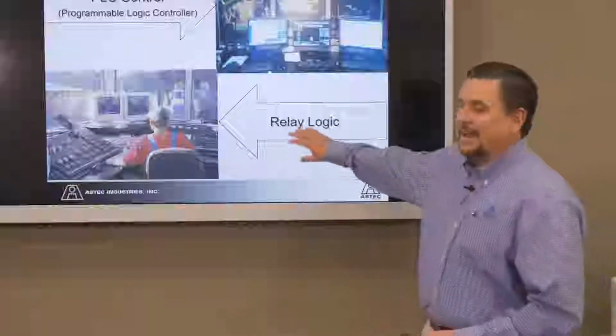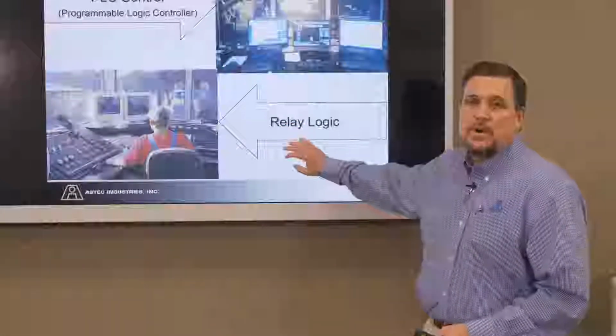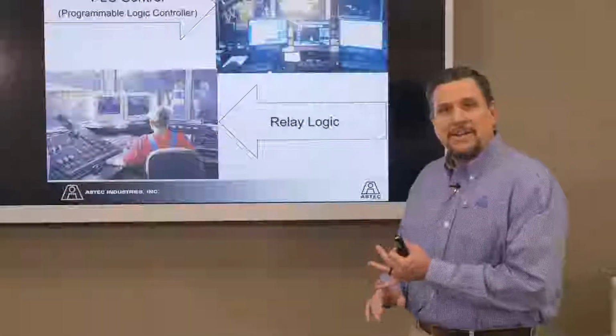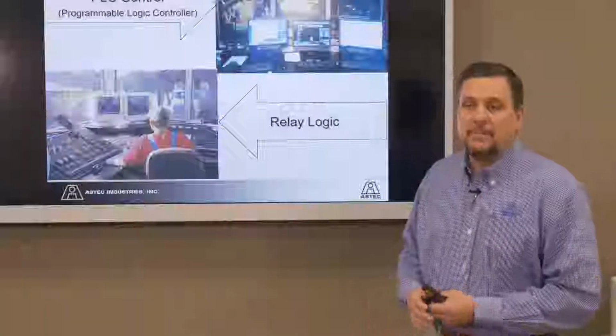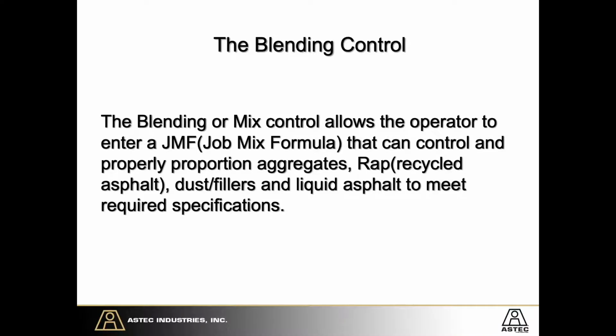Even on the older relay logic systems, when you looked at a blending control, that particular blending control more than likely had either a proprietary blending control or a PLC blending control associated with the push buttons. Some people ask, what's a blending control? The blending or mix control allows the operator to enter a job mix formula that can control and properly proportion aggregates, recycle, asphalt, dust fillers, and liquid asphalt to meet the required specifications.